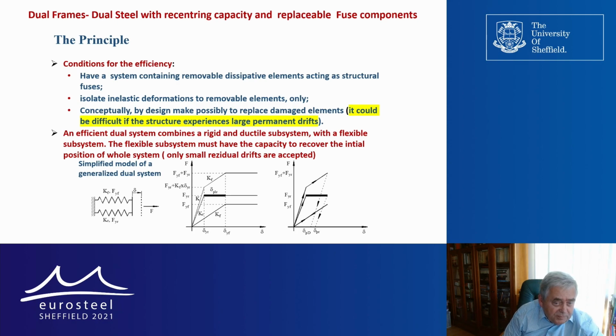We have to look at this as being the braced system, which is rigid, and the flexible one, which is the moment frame, but anyway, with the capacity of taking 25% of the lateral loading induced by the earthquake.